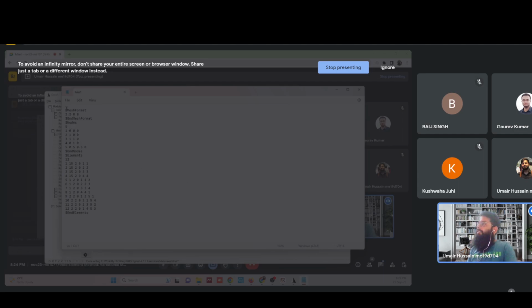So we have the format written in the version format, and then we have the node data. After node data, the first thing you see is the number of total nodes. You see we have four triangles, so we have total five nodes here, and then we have the coordinates of the nodes. Coordinate data for each of the five nodes is here. Obviously this looks like what you saw in that figure, right?